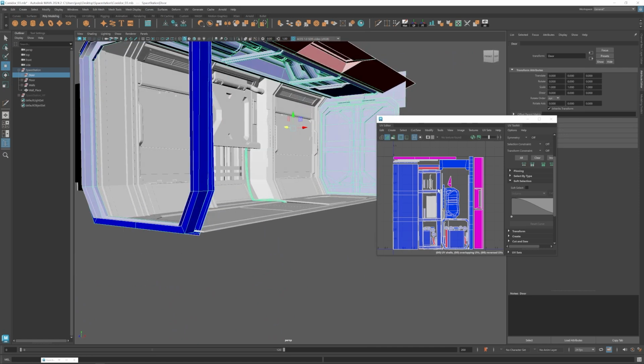It's pretty straightforward. I'm not gonna lie to you, I could have done a better job on the UV map and really taken advantage. I always tell people, if you're familiar with this channel, to prioritize that UV space, and looking at this, it bothers me. There's lots of wasted space. I could really enlarge some of these shells to get more resolution out of those materials.